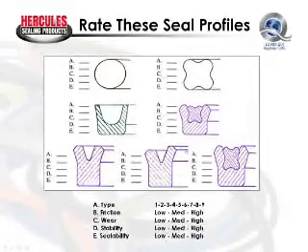This seal is our asymmetrical seal. It can be used only as a rod seal or only as a piston seal, not interchangeable as with the symmetrical. You'll notice that one lip is longer, giving us increased stability over the rectangular shape. This would be the static side of the seal. The dynamic side of the seal, the lip is a little bit thicker and a little bit shorter.